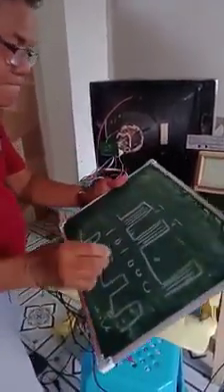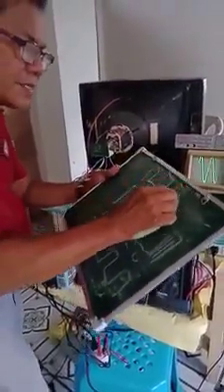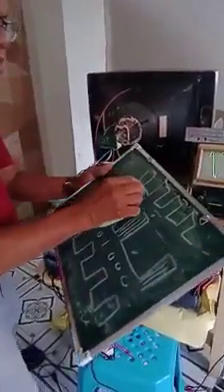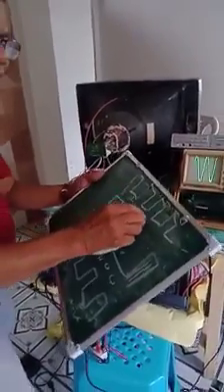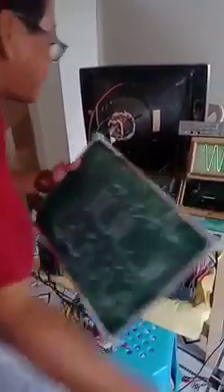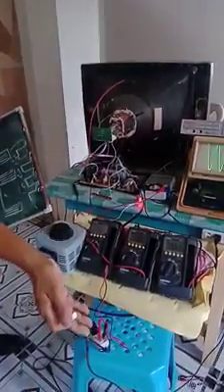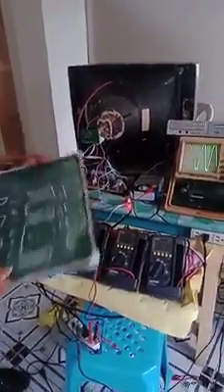For volume up, you have here the pulses 1, 0, 1, 0, 1, 0, 1, 0. Those are the binary information being submitted by the remote control to the TV receiver as it passes the infrared sensor.